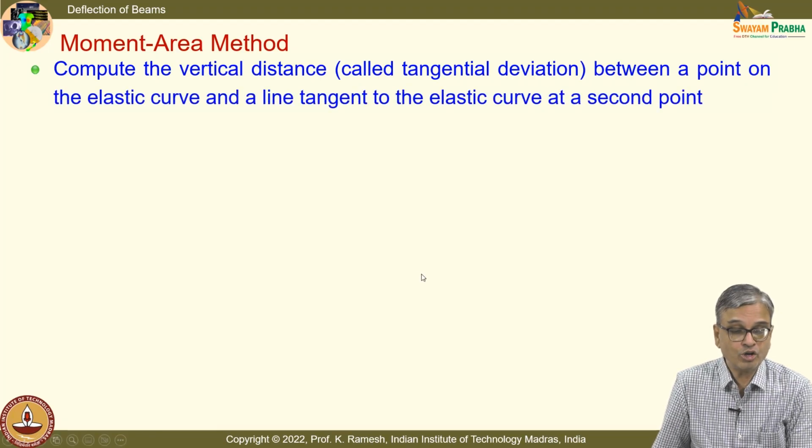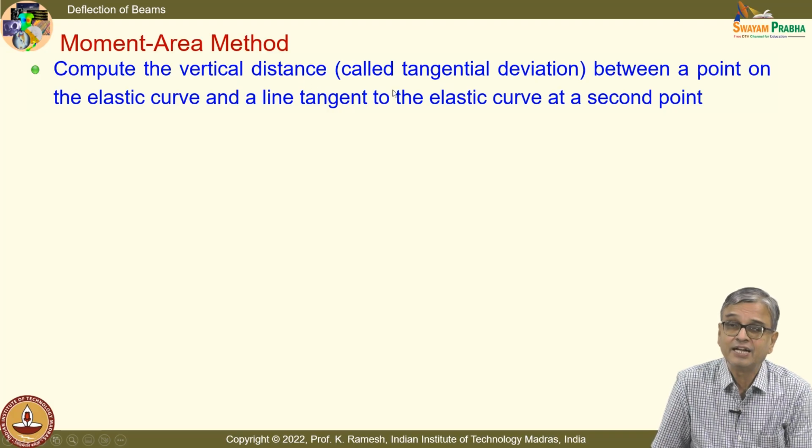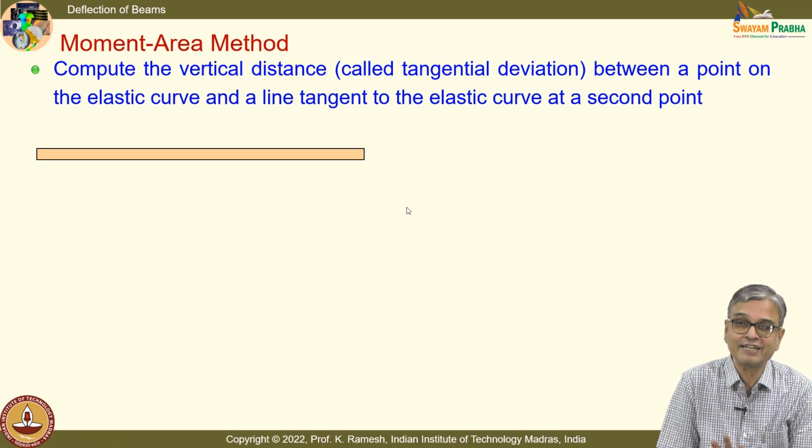And you can also calculate the tangential deviation. It is a very important aspect. I cannot find out the deflection, I can find out only the tangential deviation between a point on the elastic curve and the line tangent to the elastic curve at a second point. So, it cannot find out deflection directly, I can find out only a tangential deviation.